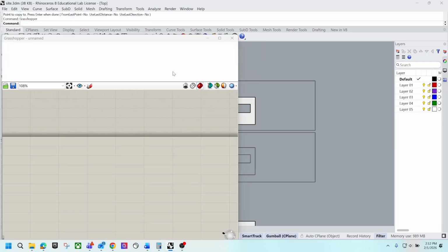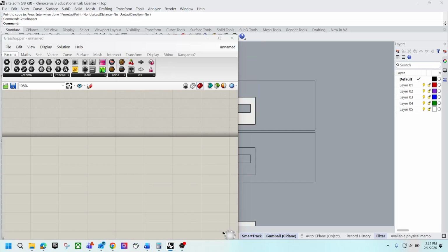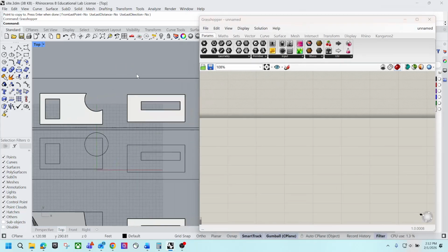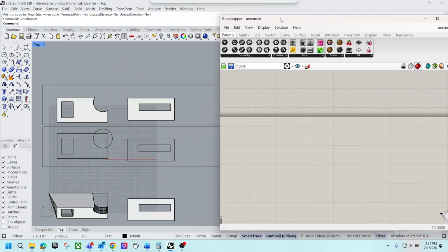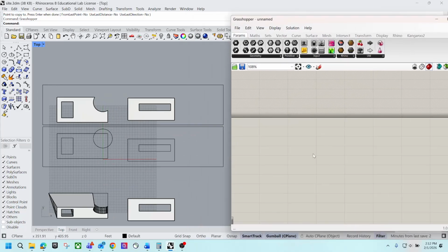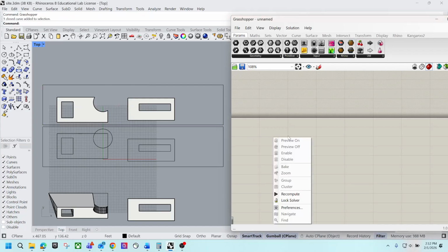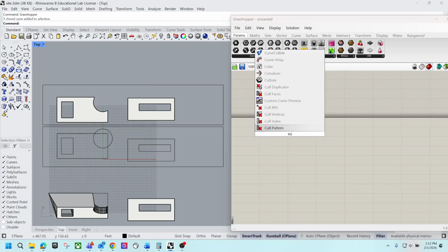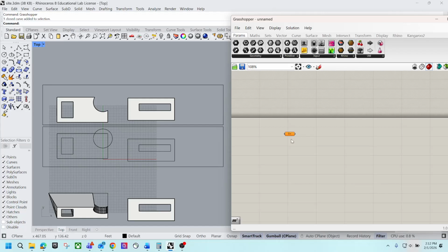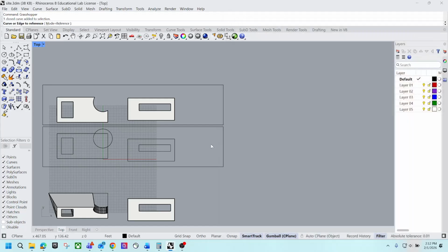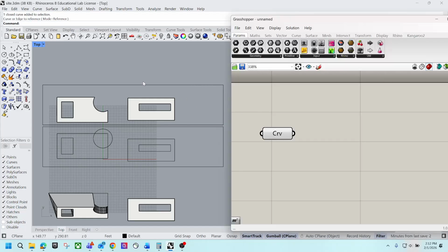So I will run Grasshopper. Not sure how much you know. It's a pretty good interface. You can load in geometry and make calculations. All right, so the first thing I want to load is this site, right? The site is actually a rectangle, but you can also do a curve. It's the same. So double click, you can pick a curve. Right click, you can set one curve. You can pick the site. So now we got the site in Grasshopper.